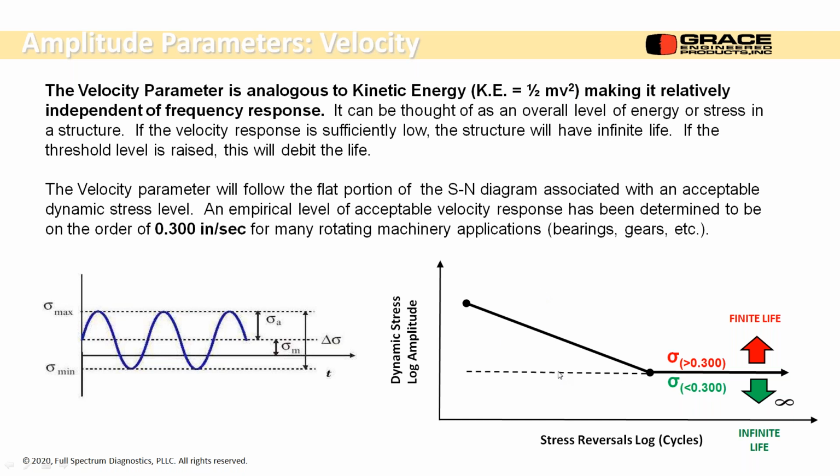And they've been doing this for a long time. So, sorry about the long roundabout way of explaining this, but that's what people still don't quite get in their heads when they quote the displacement values. You have to know what frequency it is to see where you are and what amplitude you can tolerate. Okay.